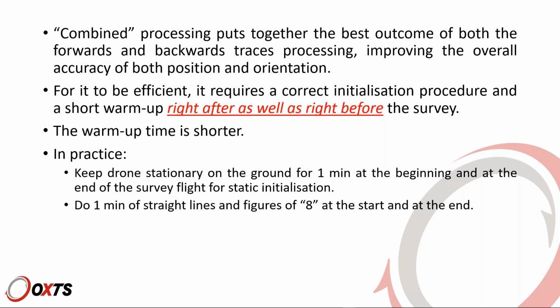For a backup option, that's dynamic initialization, end your survey with a straight line, which would be what the system would use for its dynamic initialization if needed in the backwards direction. Okay, so keep this in mind if you want. You don't have to process combined, but it does have some benefits. So if you wanted to do that, keep in mind that you can apply these two easy things at the end, so you ensure that you have a backwards trace that is as good as the forwards.